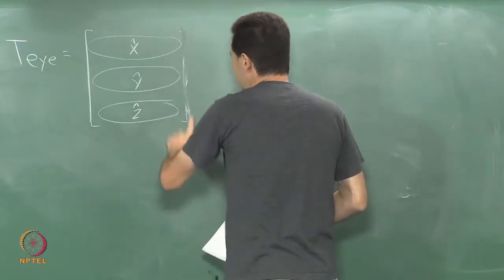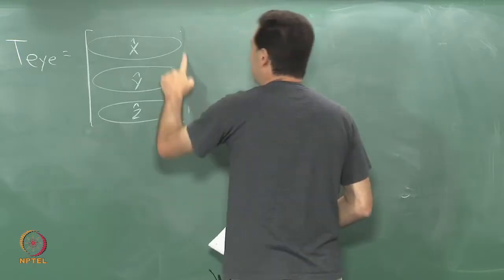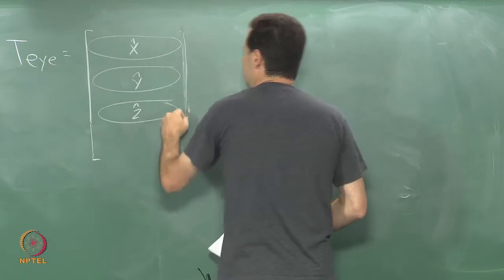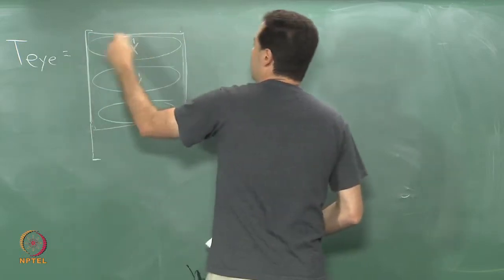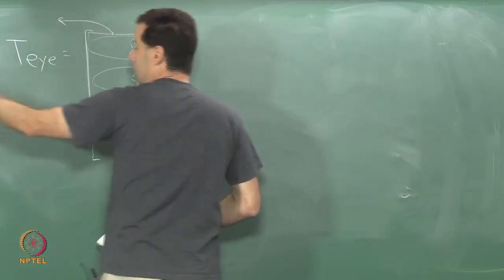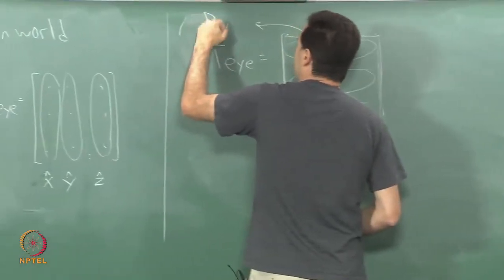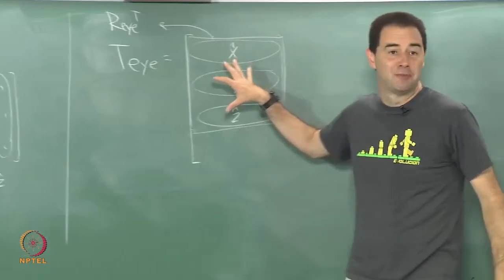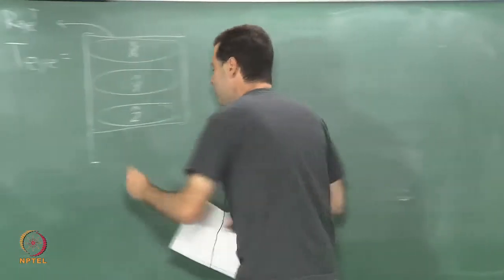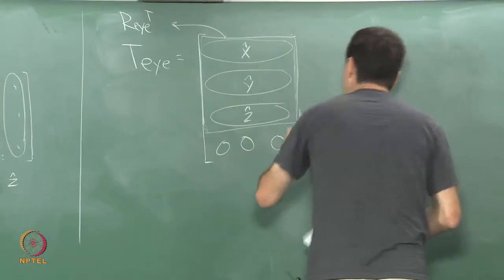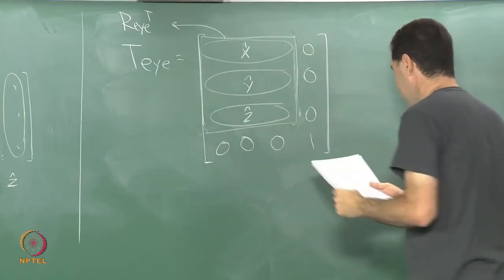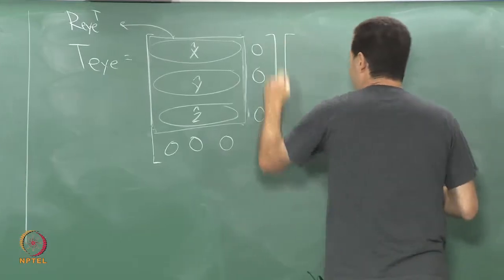Also, I need to extend this because I'm not just going to apply rotation here. I'm going to put it together in homogeneous form. So this is just the rotation part. This corresponds to that Ri there, transpose, which, because it's a rotation matrix, corresponds to Ri inverse. And then I have the remaining components, and I make this. So that undoes the rotation.